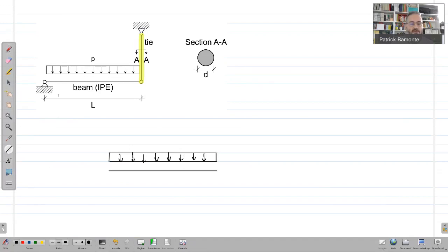And at the boundaries, we have a hinge at the first end. So there is clearly a reaction force, which is vertical. And starting off in a very accurate way, we could also mark a horizontal force, okay? We call them VA and HA, okay?